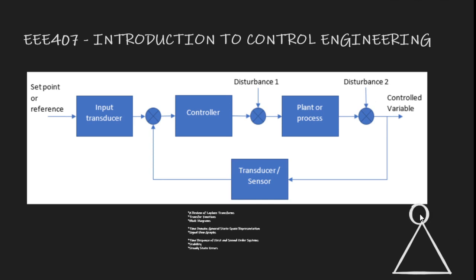Now, if the center of gravity is just above the tip, yes, the ball will remain balanced. But once you supply any input to any of the sides, what will happen? The position will keep on increasing. Now, imagine this triangle's sides were infinitely long. This ball will keep on rolling. So you supply a small signal, a small input signal, and the output position, let's say displacement is the output, the displacement will keep on increasing and increasing and increasing.